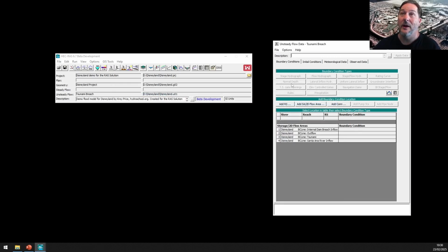So just like the geometry, never leave this description field blank here, and always update it if you make a change. I like to say something about the data source here. Where was it that you got your hydrology, for example? And then I also try to make sure that the hydrology study, the results that we're using, spreadsheets with the values that we're using, or anything else that's going to be listed here in this description is also copied into the hydrology subfolder for reference.